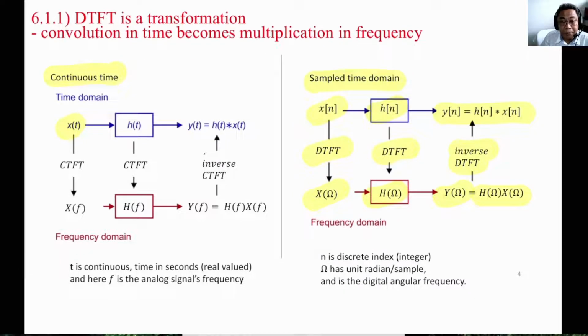So this is the primary motivation for why we want to convert something into a frequency domain, because convolution is done very cheaply. The other one, of course, as I reiterate, is that by breaking x of n into the complex exponentials, we can see how the signal is represented in the frequency domain. We know exactly which signals are summed to construct x of n. We know exactly which frequency has more power, less power, and its different phases.